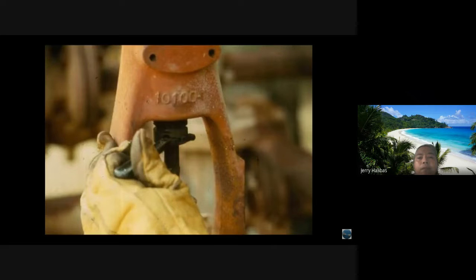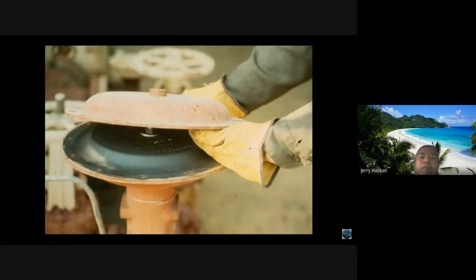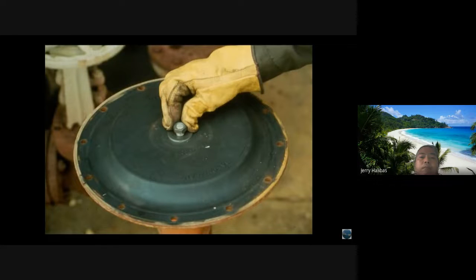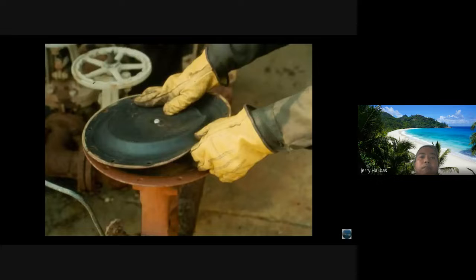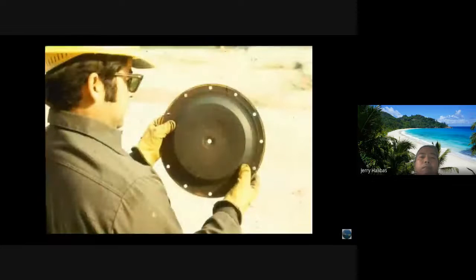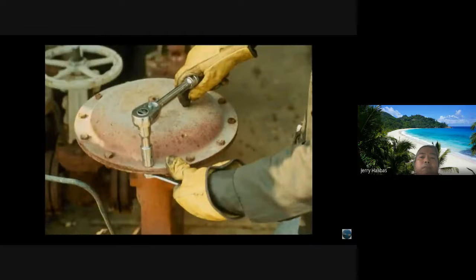Remove the tubing, then loosen the actuator spring tension by unscrewing the actuator adjusting screw. Failure to release the spring tension can result in a serious accident. Remove the upper diaphragm case, the actuator stem screw, and the diaphragm. Inspect the diaphragm for splits, holes, cracks, or tears. Replace the diaphragm if necessary and reassemble the actuator.